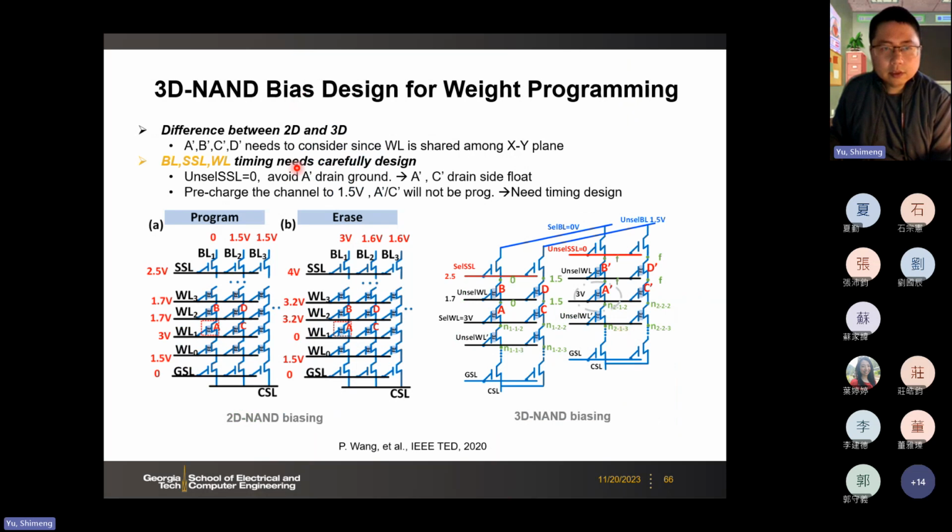So here then, again, how do we individually program those cells? This needs very special timing. Because, as I said earlier, we have to use a string erase to individually program and erase. So we have to bias different word lines and different bit lines in a certain way, in certain voltages and also in certain timing, to have only the selected cell have the appropriate voltage. I'll skip the details, but my point is that we have to do this very carefully.